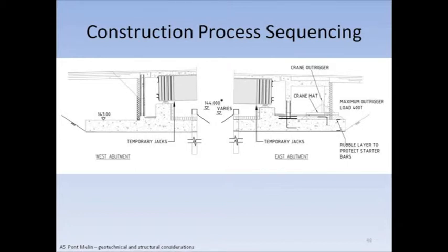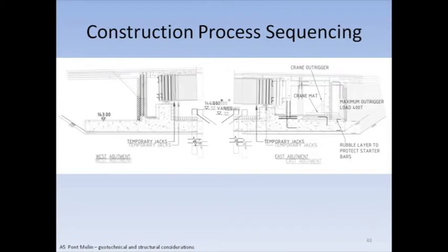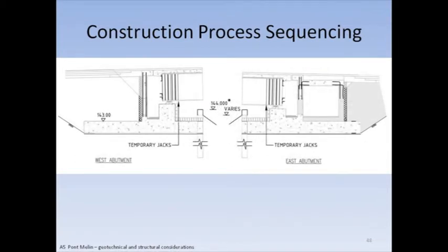And in fact, it was something that was fed back into the geotechnical design as to how that sequencing of events would happen, such that 400 tons could be accommodated and the settlement would occur with loads being put on at the front and the back of the base. The beams were lifted into position but placed on temporary jacks.